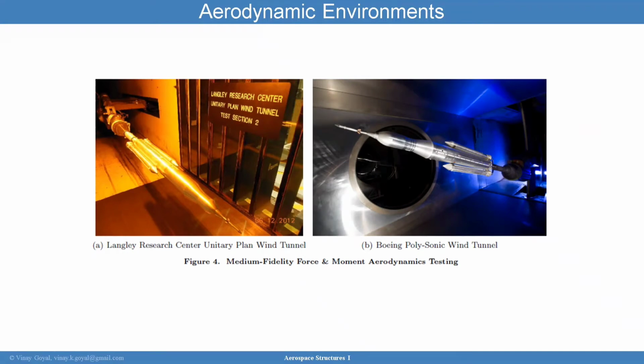The use of CFD has an important role in launch vehicle development, and it's an integral part of coming up with these load environments. But wind tunnel testing provides a cost-effective approach to accumulating the large amount of data that's required to understand the force and moment databases used for the design. And also, when you compare this testing, it can increase the confidence in the CFD analysis for looking at aerodynamics at various times of flight.